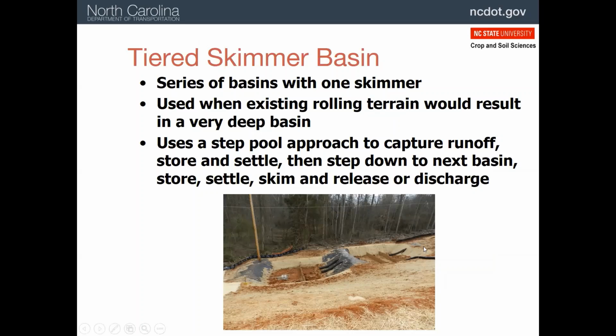Runoff enters the upper basin, as you see here, often through a pipe or a low spot, and then the water goes through the fabric, through the baffles, as you see here, and then it crosses over into the lower chamber, and sometimes there's 3 or 4 of these chambers, and again the water passes either through a pipe or across the dam. There may be a low point here in the dam, and we see another baffle and then a skimmer here.